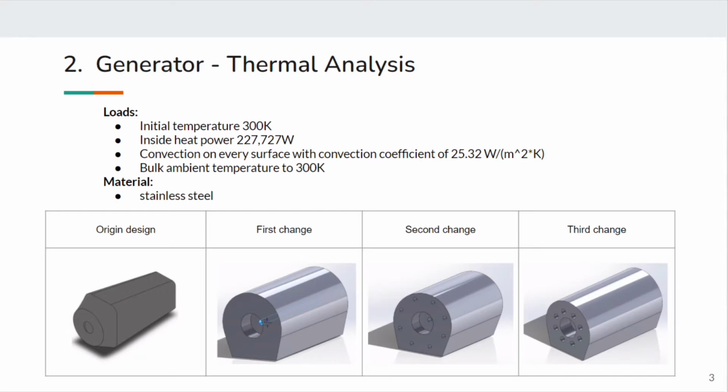Heat will be introduced by high current flow during turbine operation, so thermal analysis is performed to study the effect of heat on the generator. For the simulation, we add heat generation at the center to simulate power loss, and convection to all other surfaces to simulate heat dissipation. The original design is just the outside chamber, so we modify the model to be similar to the real generator.